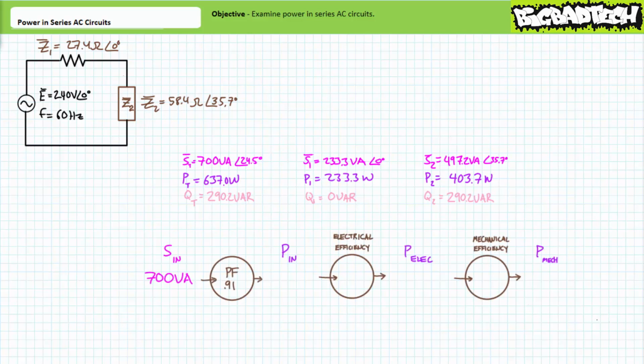This is where it's helpful to think of power factor, electrical efficiency, and mechanical efficiency as subsequent hoops through which apparent power must jump to yield usable real power output, where power factor is the first hoop, electrical efficiency the second, and mechanical efficiency the third. This illustrated example really only dealt with electrical power, but let's say the motor in question is driving some gearbox that has some mechanical inefficiencies like friction or misalignment of the shaft.